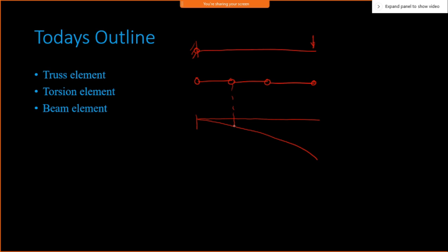When it deforms, it will show me two parts. One is deflection in this direction. Another one is a rotation about this. The rotation is nothing but theta, and that rotation is determined by the slope of this. That is also called du by dx, or if it is 1D, I can write it as du by dx. This is nothing but the slope boundary condition.